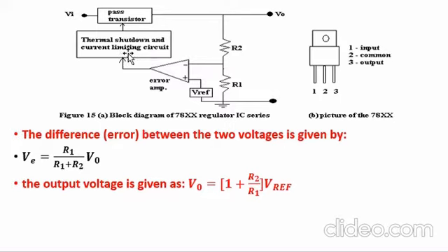And here we have 2 resistors, R1 and R2, and they are connected in what we call the potential divider. And this is my operational amplifier. Its function is to compare the variable voltage here and the reference voltage. When the two are the same, then the error should be equal to 0, and the output will be maintained. But whenever they are different between the reference and this, it will now supply this one so that it will adjust this to maintain it at the fixed value.